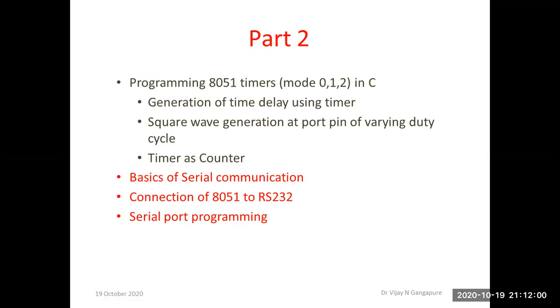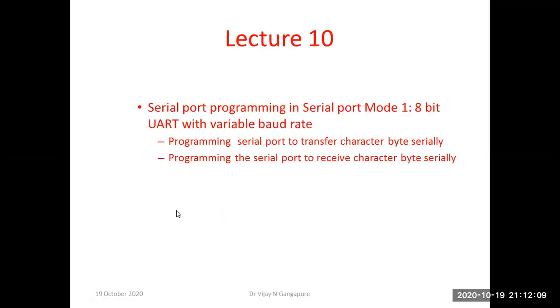We studied basic things in how to program this serial port of 8051, and now we are actually going to study the programs on mode 1 of this serial port, that is 8-bit UART with variable baud rate.